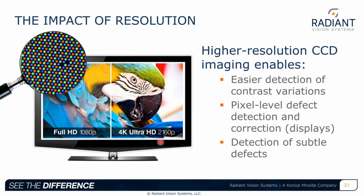Finding pixel level defects and correction of displays. Having more CCD pixels is very important, especially as the devices being measured get higher and higher in resolution. As you want more measurement pixels, you want more than 1-to-1. So you want as many measurement pixels as possible across one of your device pixels. And again, having higher resolution is great for detecting very, very subtle defects. If you just see a small dip, you wonder, is that just 1 CCD pixel? But if you have 10 across it, you can really be sure that dip is there.